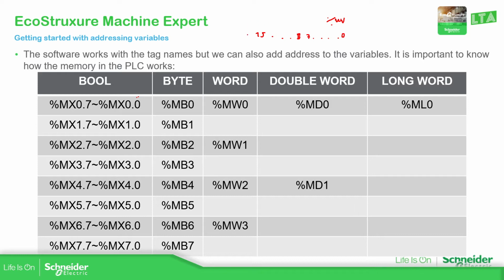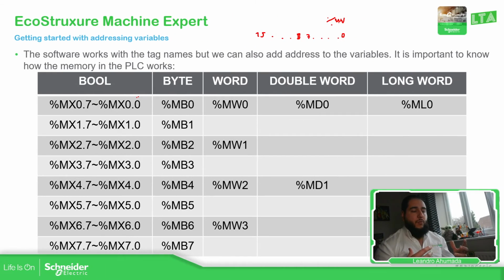We're going to see this when we're trying to communicate with the HMI. So in the PLC, it's not divided from 0 to 15, it's divided in 2, because the word that we have has 2 bytes, and there are 2 independent bytes that we need to read over here.